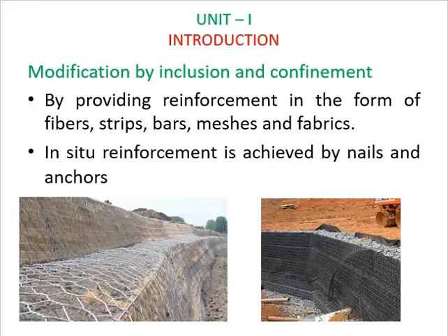Then another method is modification by inclusion and confinement. The geotechnical properties of the soil can be improved by providing reinforcement to the soil. This reinforcement may be in the form of geosynthetics, fibers, strips, bars, meshes, or soil nails.